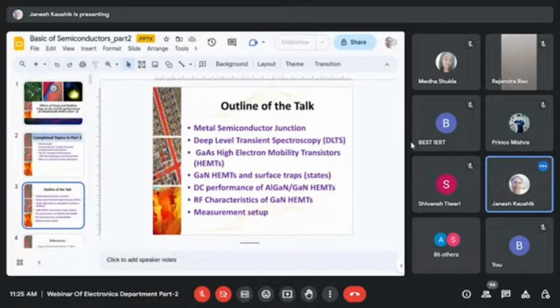In today's topic, I will cover one more measurement technique, that is deep level transient spectroscopy, DLTS. It is an electrical characterization tool, and we do it in our lab regularly. It tells where the trap is, what its energy level is, and what the capture cross section is. That is from the transient measurements of the capacitance as well as current. So it is our wish, depending on the device, what we want to measure. Sometimes we do both. Sometimes it is not possible to measure the capacitance due to higher leakage currents. Then we do only transient current measurements.